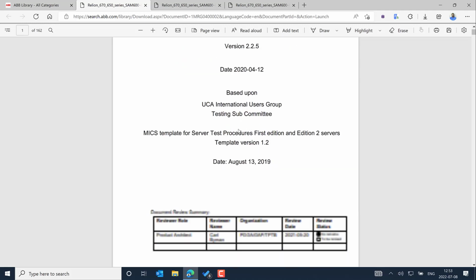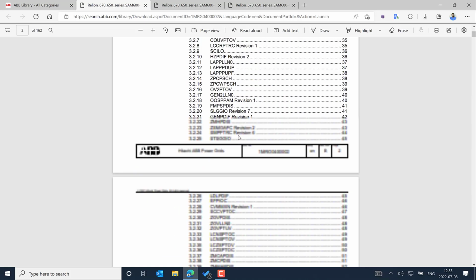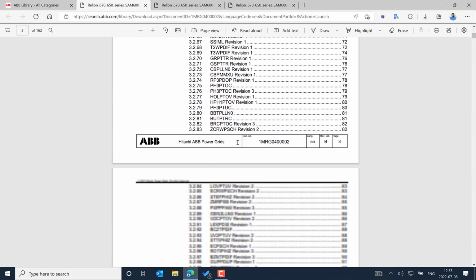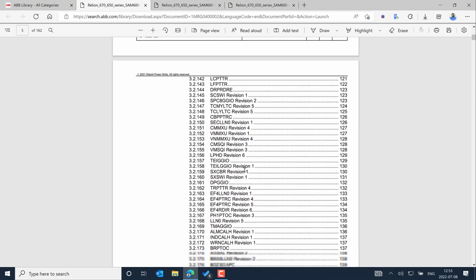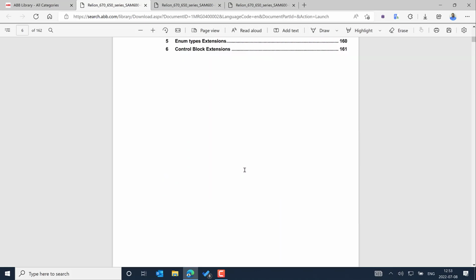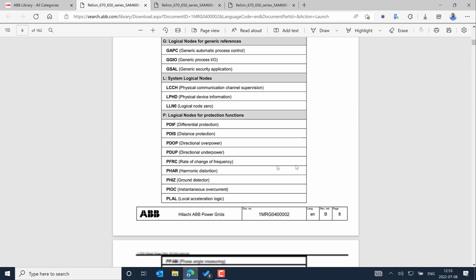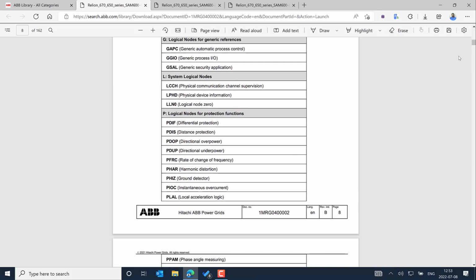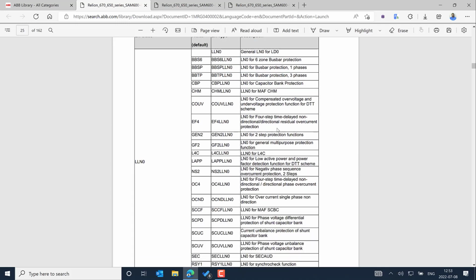It has the functions, and those are the logical nodes that are available in the different types of IEDs, the function blocks in this case, and in other products, basically those are the function points or functions, represented as a logical node in the 650 terms. So it has the logical node, data object, and the data attribute, and the property of the data attribute. Basically, the explanation for the implemented function and the description. This information we can also get in the XML file from the ICD.